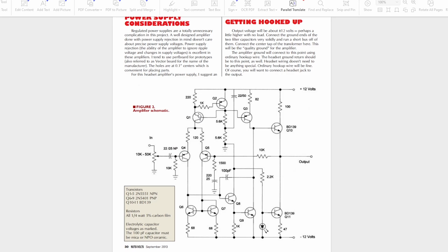So here's a look at the schematic to this amplifier, and one would be forgiven for thinking immediately that this is a typical Class AB amplifier with a quasi-complementary output stage. Well, it's not. Everything here is conventional, and it's using quite a few elements of Douglas Self design, like this emitter follower in the VAS circuitry here, and current mirror.